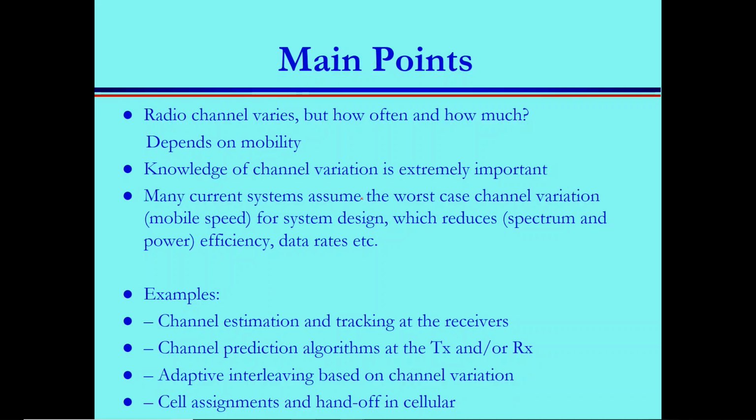So to avoid this problem, just do exhaustive measurements for your channel, and from these measurements you find the maximum delay spread, maximum Doppler spread, and design your system according to this situation. Of course, this system, although it will be robust under any situation, is not efficient. Why? Because there are times where you don't have this much spread. Why do you need to squeeze and limit yourself with this design?